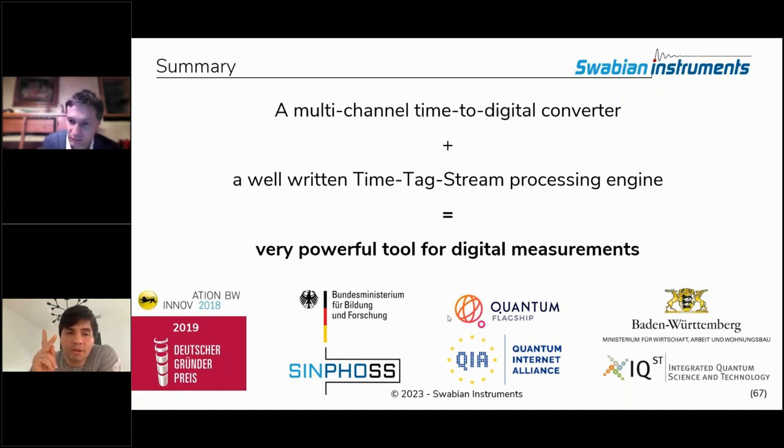So would that also be bi-directional, you know what I mean? Basically the start and stop can exchange, right? You can get the stop before the start, like they call bipolar TDCs. Would that be bipolar? I guess yes. What we will be doing is a multi-channel one. If you run it on a base clock, let's say a gigahertz clock, and you have two independent inputs, the start and the stop, you could interchange them, so they're completely interchangeable. Yes.